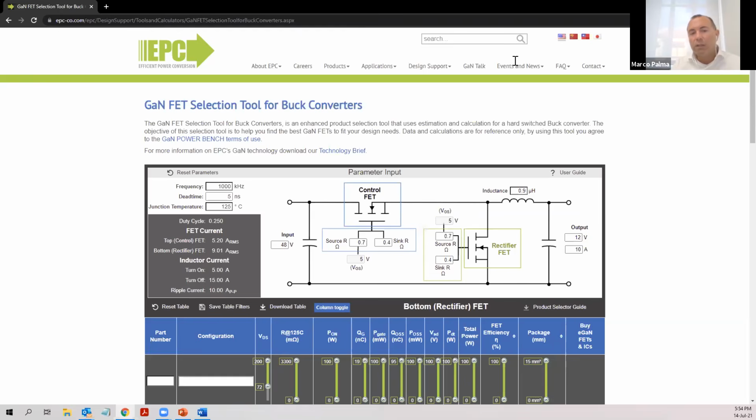But usually what I do for that case is there are a lot of websites that do this calculation for you. Even the CAD tools, like Altium and things like that, can do it. But usually I go on a website and look for PCB trace current calculators, and then put in the numbers, even the temperature, which is important because it slightly changes the current.